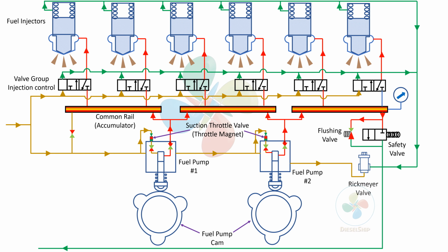So in a conventional engine, we had that kind of pressure block or a back pressure valve or a pressure maintaining block, whatever you call it. Basically, it connects inlet to outlet to maintain pressure. If the incoming pressure is too high, it opens up so the required pressure is maintained through the engine. If it is too low, it closes to increase. So that's how it operates. It is purely a mechanical valve, right?